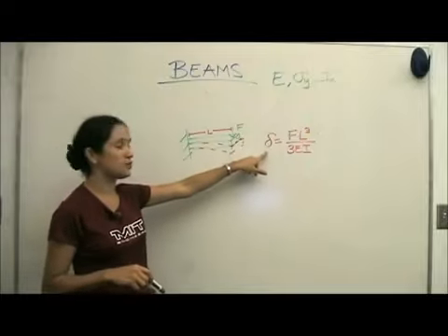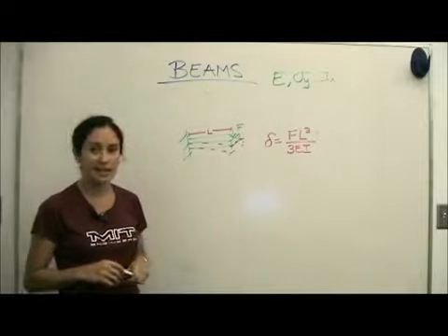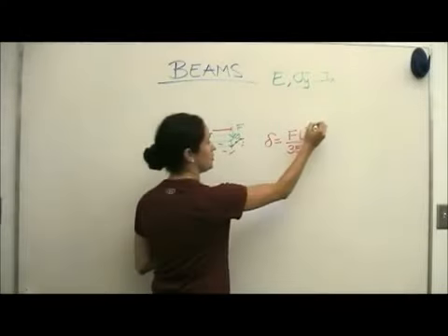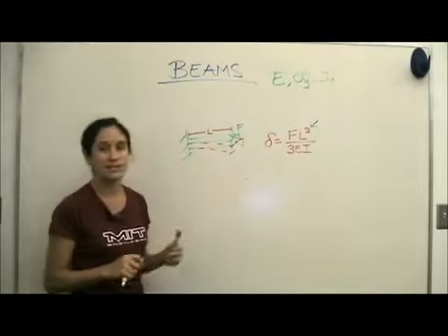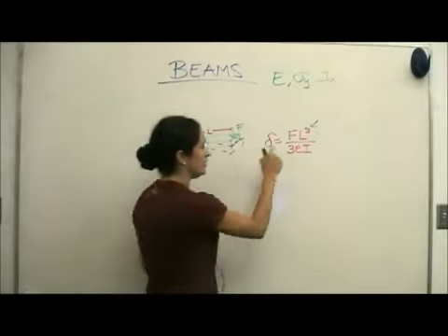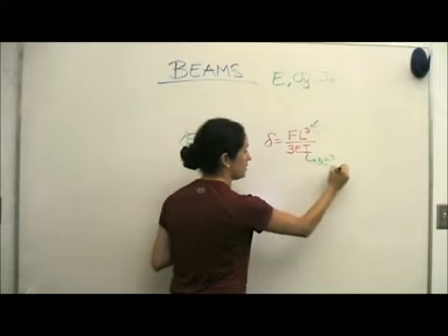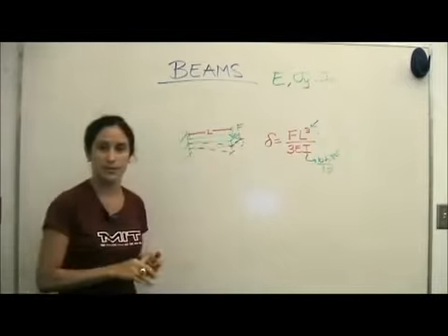So this is our equation for the deflection of the tip of the free end of the beam. And again, the first thing you should notice is this cube term again here, which tells us that the length of the beam is going to be very important in calculating its deflection. If we were to expand the area moment of inertia, which said bh cubed over 12, again, the thickness of the beam is very important.